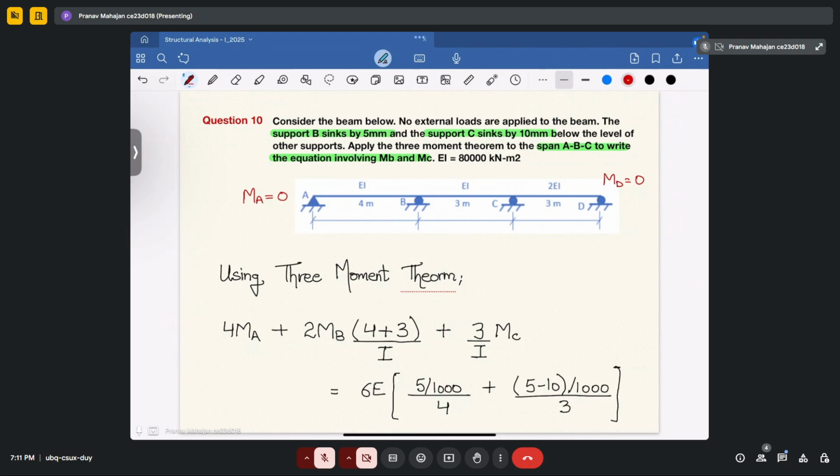Then we have utilized the same principle of force method. How have we done it? We have first changed the redundant structure into a primary structure by removing the redundant forces, or you can say redundant reactions from the beam. Then we have solved the primary structure and we have got the deflection at the corresponding point.